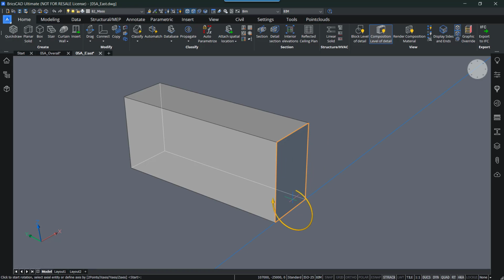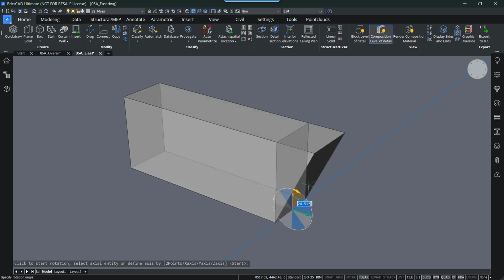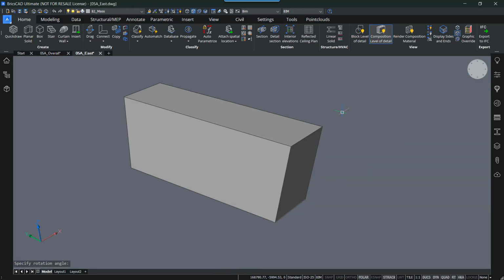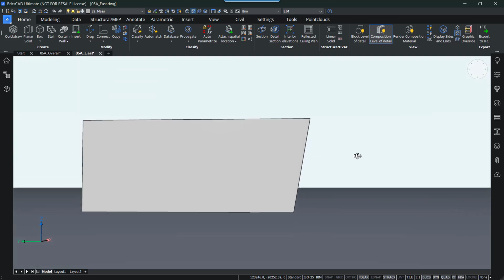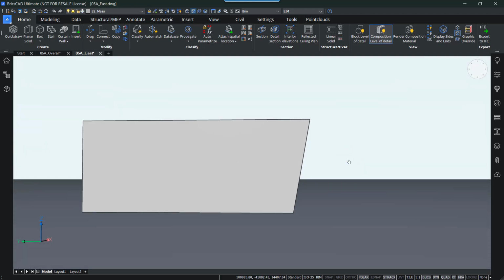So in this case I want the axis to be at the bottom, so you can click on that, and then you see now I can have a rotation of that surface to a certain degree. So this is a very clear preview for that. So in this case let's do 10 degrees going out. So we can manipulate our block like this. So now you see if I go to the side, it's a bit rotated.